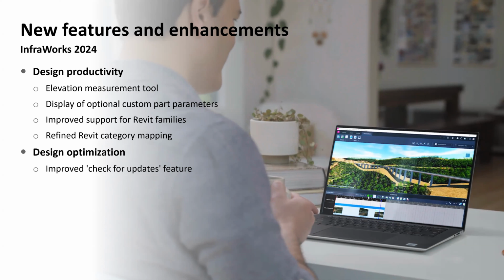So these are very significant improvements, which ensure that most of the Revit families can now be interpreted and worked with within InfraWorks. And right now you're also able to do category mapping. So you can categorize them, whether they are girders or piers, based on the specific structural component of the bridge that you'll be having within the model.